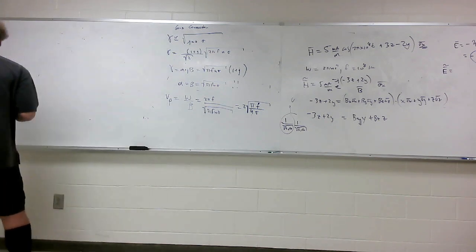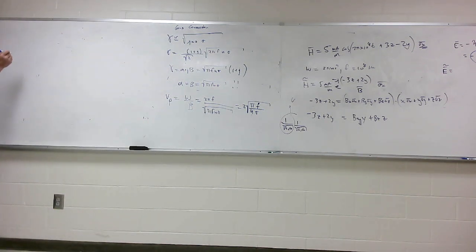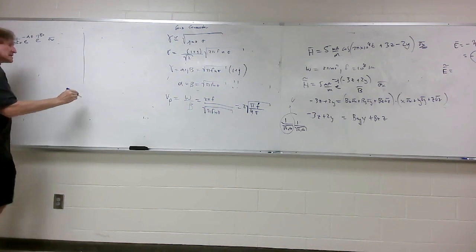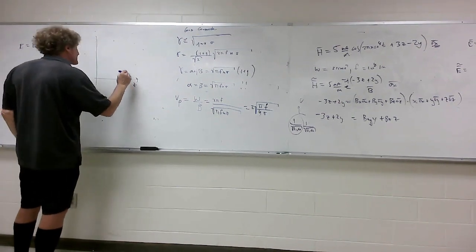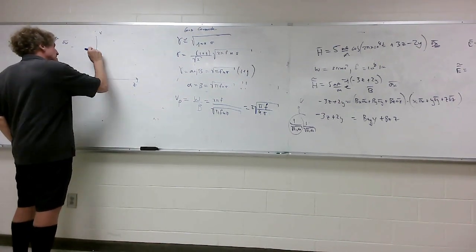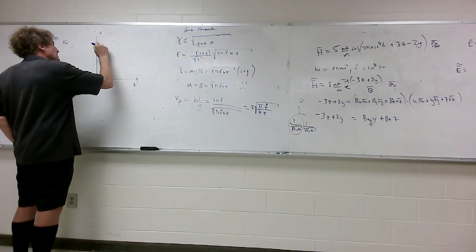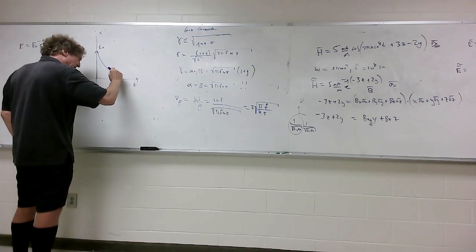When we have the equation for the electric field, I'll use Whitworth's notation. He says the E field is going to be some E naught. Now he's talking about a plane wave in a bar of copper. It would be e to the minus alpha z, e to the minus j beta z in the a_x direction. So he's really saying, if this is z and this is x, that the E field is in the x direction, but it's going to decay like crazy.